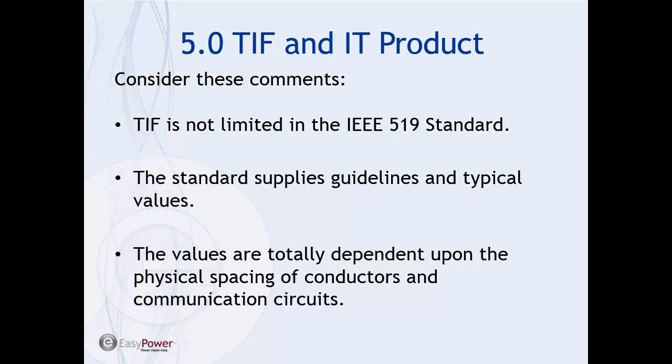These values are useless on any type of in-plant feed or any type of overhead distribution feeder if there's no communication circuit on it. The only time we need to consider these two values is when there really is a communication circuit running in parallel so that it mutually couples with the overhead conductors. That's really the key application here.